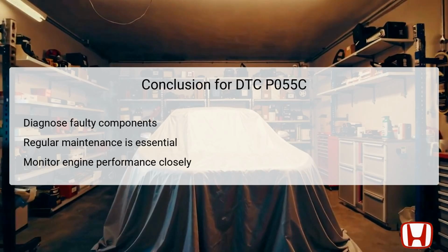The outlined troubleshooting steps guide technicians through a structured approach, from verifying sensor voltages to examining circuit integrity and diagnosing the PCM. Additionally, implementing a preventive maintenance strategy is essential for minimizing future occurrences of this error code, encompassing regular oil changes, monitoring oil pressure, and inspecting wiring.